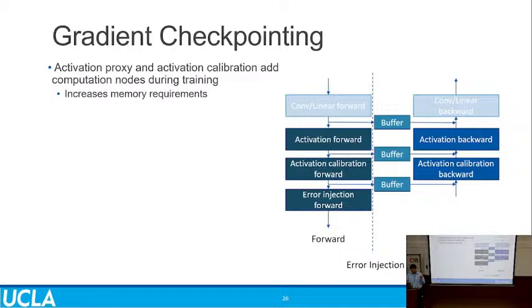And if you start storing the full RNGs, then you quickly run into memory requirement issues as well, right? Our streams are packed bits. So instead of storing 1 bit, if you store the whole stream representing the integer, now I'm using up much more space in memory. So even that doesn't work out that well. So we store as compressed fixed point throughout the training, and modeling of the stochastic streams is done using these other tricks.